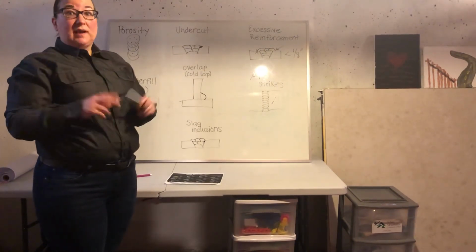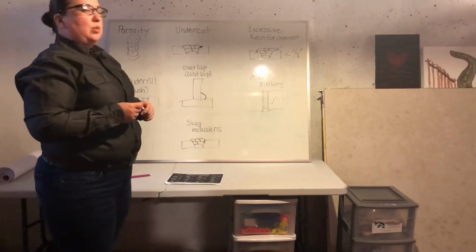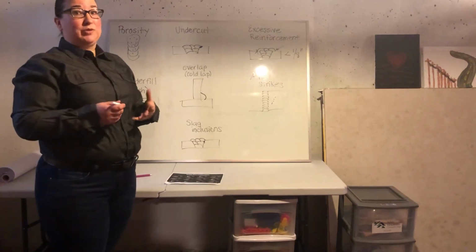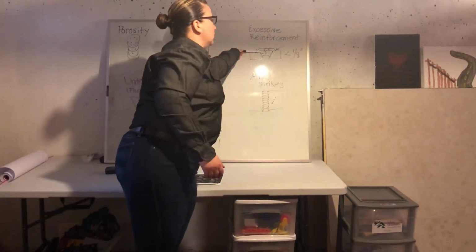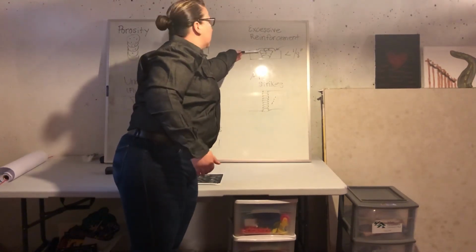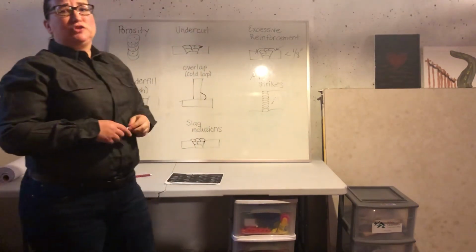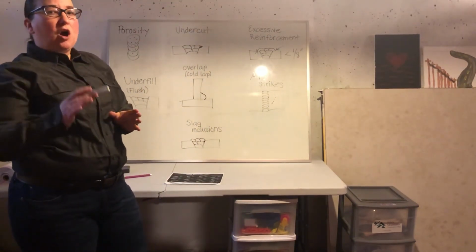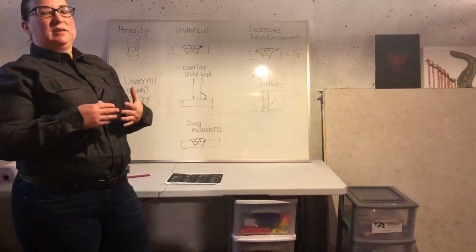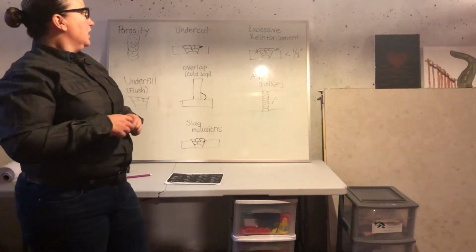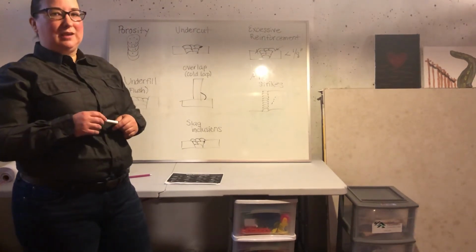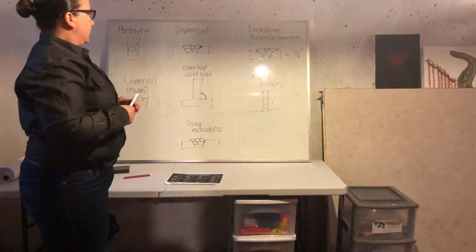But where we're leaving something as welded, we want to make sure that we're not putting too much of that reinforcement there. And we can get that excessive reinforcement through a couple things. One, if we haven't planned our trip out to the top well enough, we have to put too much weld on the top to fill it in. Another thing is if we're traveling too slow, once again, we're getting a very convex bead, and it's going to look kind of piled up on top rather than blended between our other beads and our base metal. So we really want to aim for that pretty reinforcement on the top. We want it to be visually aesthetic.